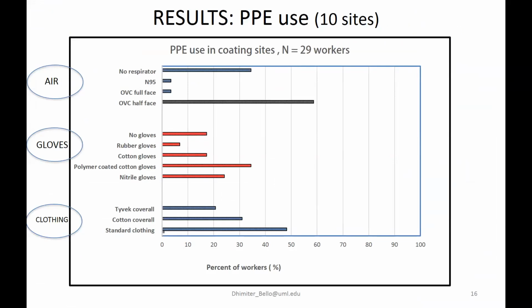But I do think that in terms of the aliphatic isocyanate monitoring results, equivalent data could be generated using samplers such as the ASET sampler for aliphatics, and based on prior work we've done and comparison with the reference samplers such as impingers, one could also use a treated filter with field extraction, although I think the ASET sampler or a SIP10 would be, in terms of the design, the superior samplers for this particular application. I hope this answers the question.